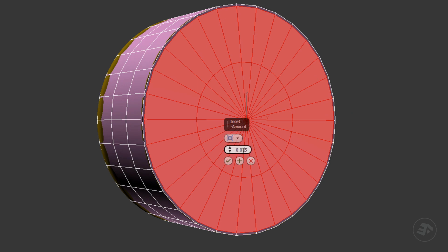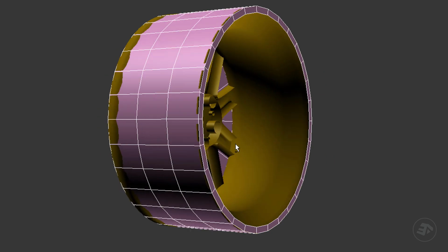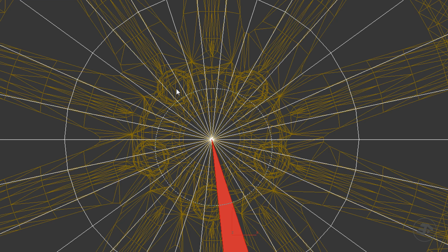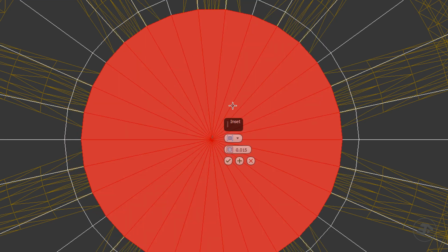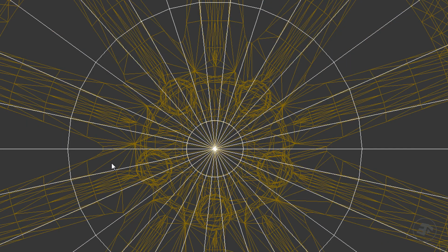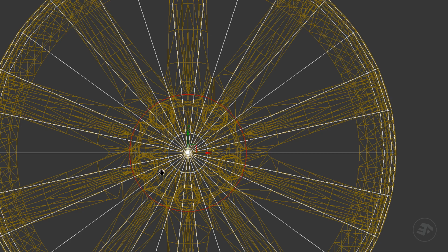Insert a loop at 15 mm. Then, delete the selected polygons. Insert a loop to mark the logo, and another one for the mounting area. We do not need this origin loop. Hold Ctrl, then hit Backspace to remove the loop with its vertices. We will add others at specific locations.